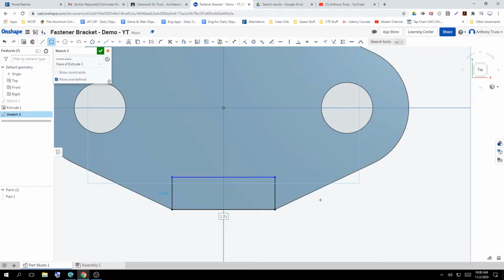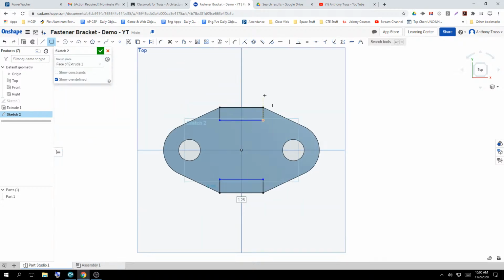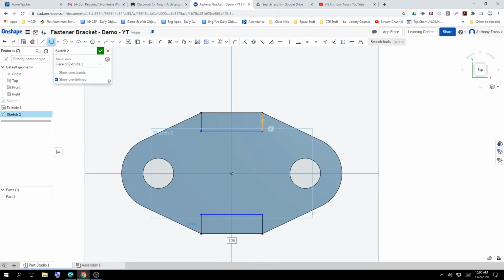It'll stay attached, okay? The only thing I need to do is dimension that this line and this line is 1/2 inch, and we extrude it up, okay? And we're just about done. We're going to make use of a fillet, which rounds sharp corners, okay? So I'm going to press D. We're going to do 0.625. Oh, I'm sorry, not 0.625, 0.5. All right, there's our 1/2 inch. I'm going to do the same thing on the other side.